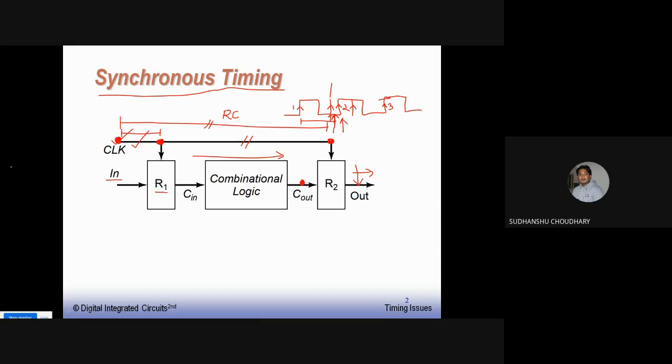So clock uncertainties or clock skews are a result of delay mismatches between the clock source and clock destinations. The designer has to overcome these issues by some methods, for example clock routing techniques, such as the H-tree clock distribution technique, or many more. That is how the designer has to equalize the delay from the source to the destinations. Otherwise this kind of situation can appear, the entire circuit operation will be disturbed, and the circuit will result in a waste circuit.